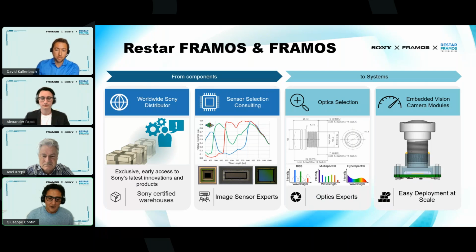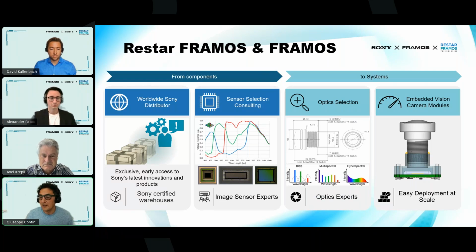that we selected together, with the proper interface also, because system means also we need to transfer the information from the sensor to some host, to some software, and so the low-level interface of the sensor, MIPI, SLVS-EC, and then the driver on some host that could be NVIDIA or embedded system like NXP or Qualcomm, or everything that you need to get the image into the memory. And most of the time, the image must also be calibrated and must be tuned.